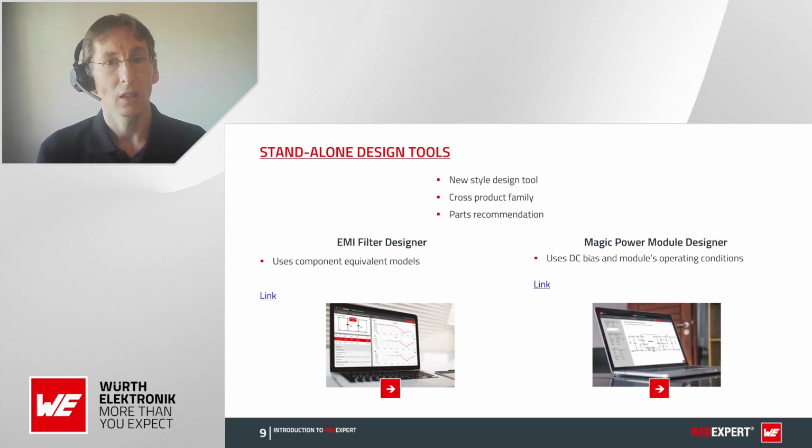Lastly, we also have some standalone design tools. This is a new type of design tool, which is really focused, starting not with the product itself, but starting with the application. These tools recommend cross-product families. So we recommend a combination for the filter designer, a combination of inductor and capacitor, and for the power module the different capacitors. The EMI filter designer uses the component equivalent models, so all the parasitics, to calculate the best parts for you and recommends the 5 best parts. And the same with the Magic Power Module, we're using the DC bias from the capacitors to calculate which ones are suitable to use with this module.